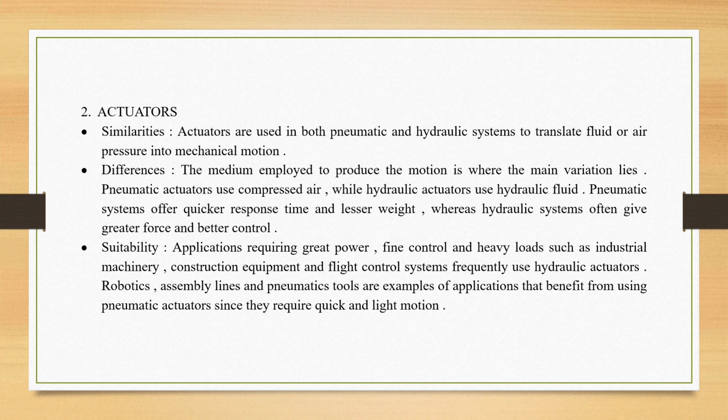For suitability, applications requiring great power, fine control, and heavy load, such as industrial machinery, construction equipment, and flight control systems, frequently use hydraulic actuators. Robotics, assembly lines, and pneumatic tools are examples of applications that benefit from pneumatic actuators since they require quiet and light motion.